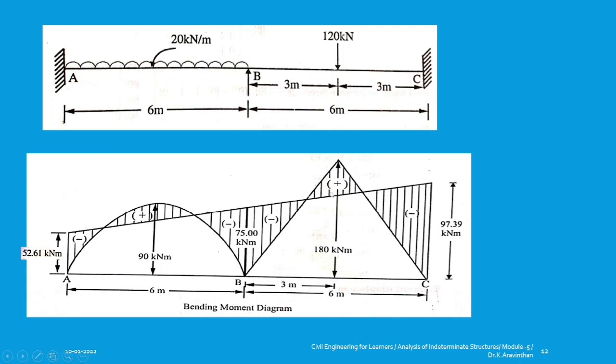The positive bending moment can be found out when you consider it as a simply supported beam. So the structural analysis here is to find the negative bending moment. This needs a technique, and you have 5 techniques. Either it might be Kani's method, you have 5 methods. So whatever your method, you have to find the negative moment. So this is your case.